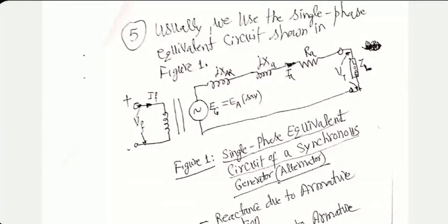XAR actually is a hypothetical parameter, while XA is representing the actual inductance of the stator windings. XAR is modeled theoretically as well as experimentally, but as far as you are concerned, this value will be given to you. So in the equivalent circuit, we show the reactance produced by the armature winding plus reactance produced by the armature reaction plus resistance produced by the armature winding, single phase.